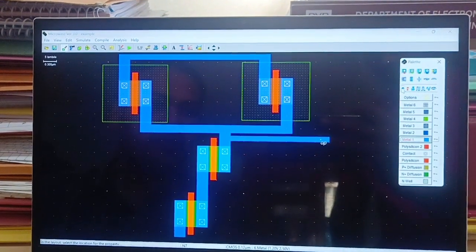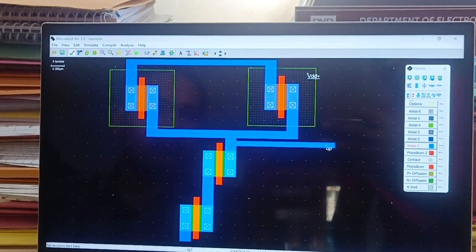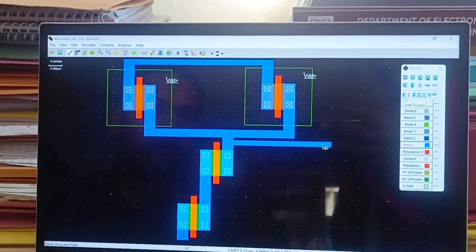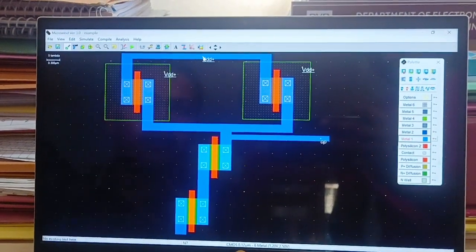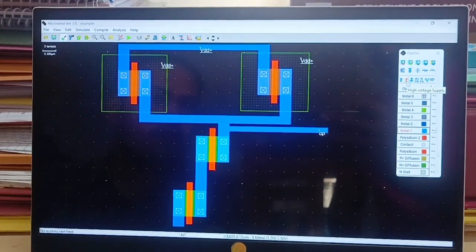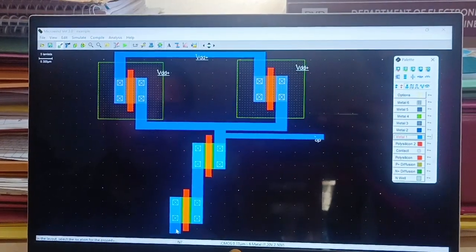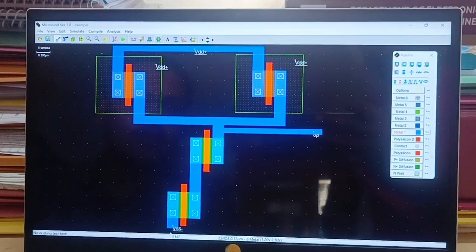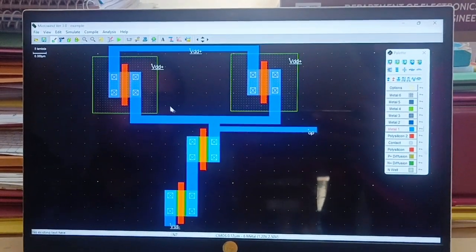So ये VDD हमारा VDD NVL को देना पड़ता है, दोनों NVL को देना पड़ेगा, तब जाके PMOS के पोलैरिटी आ जाएंगी. सेकेंड, इनका जो कॉमन टर्मिनल रहता है सोर्स, उसको जो ऊपर VDD लगाना पड़ता है, दैट आई विल प्लेस इट हियर. सो ये VDD का काम हो गया. नेक्स्ट ग्राउंड टर्मिनल, ये थर्ड वाला ग्राउंड का ऑप्शन है. दिस शुड बी कनेक्टेड टू लास्ट पार्ट ऑफ द ट्रांजिस्टर. तो दो एनमॉस जो बना है एक के बाद एक सीरीज, उसमें लास्ट वाले जो है वहाँ पे उसको मैंने ग्राउंड कर दिया. नाउ इनपुट इज रिमेनिंग ओनली, रेस्ट ऑल इज डन.